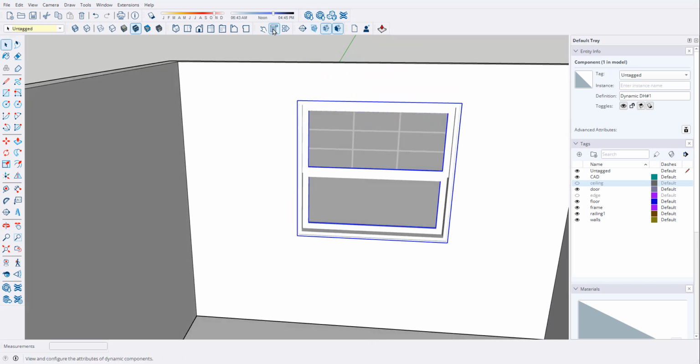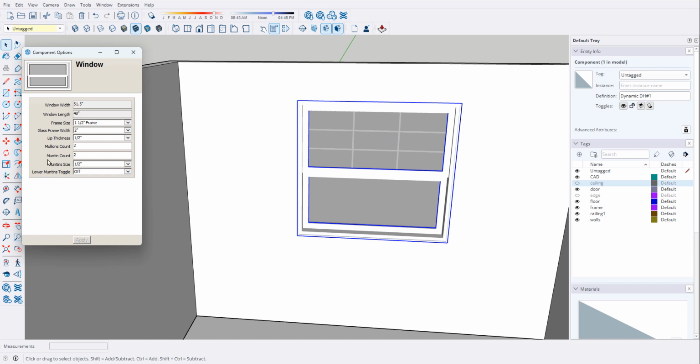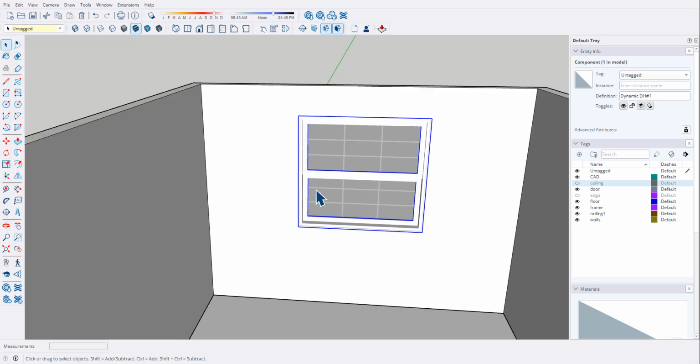And then I go to these properties here, and because I selected this, I can say if there are mullions there, and right now there will be, so I'm going to do on for the bottom mullions. Click apply, and now we've got mullions top and bottom. Otherwise, just say 0 or whatever number it needs to be.